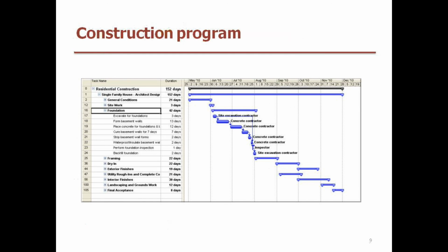As well as costs, there's the construction program, determining where the different activities of work are being carried out, the method of operation and duration. This is a very important tool, and can be as simple as a bar chart, or shown as a critical path network as well, with all the activities, the earliest start, the earliest finish date, and so forth. And again, any changes that are introduced into the construction, how that's being incorporated and demonstrated in the construction program, and how it's going to be managed.